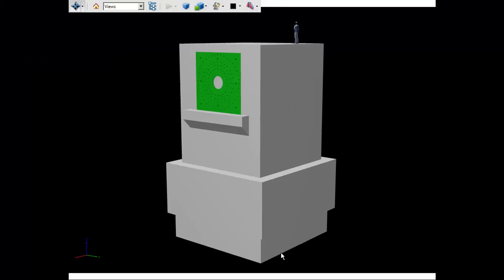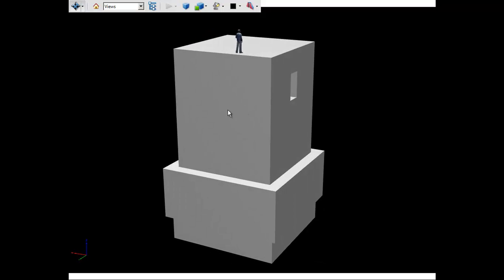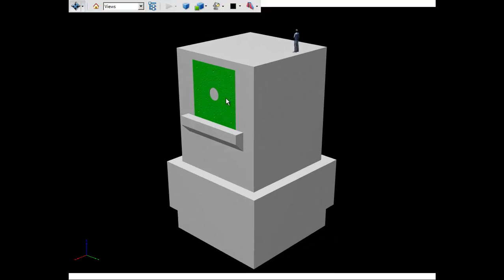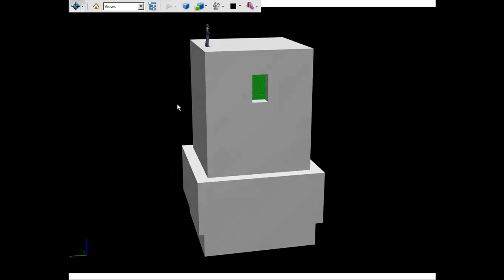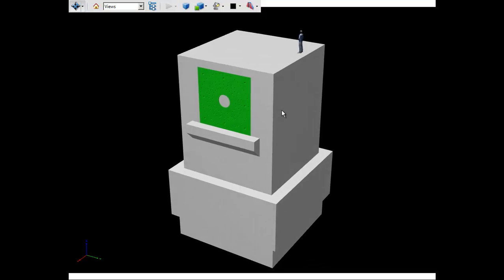this is what the foundation, so this was pinned to the bedrock as it comes up. It had a shoulder coming out. This is what actually sticks up above ground, is this little ledge, and here's that bolt pattern. This is what they're going to hook their windmill blades to. You can see how this is set up, and there's actually a door in the back that you can walk into with a set of steps down. So when you're hooking a windmill blade onto the end of this piece, you can actually have somebody inside holding the wrench for you as they're bolting this on to tighten up the blade.